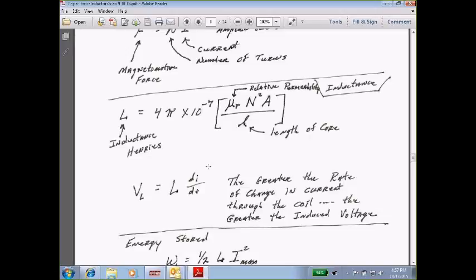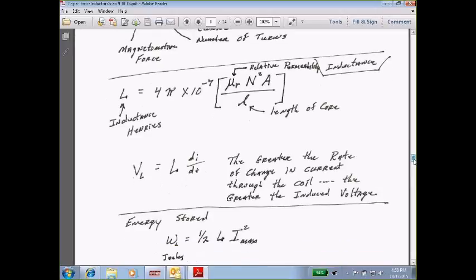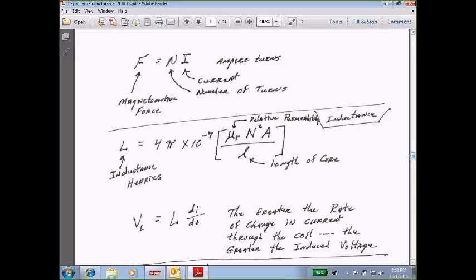That's why, for example, if you're using an electromechanical relay, and you have that coil of the relay controlled by an electronic device, a transistor, you have to have a diode strapped around that coil, or the inductive collapse of that induced voltage will actually burn up the transistor.